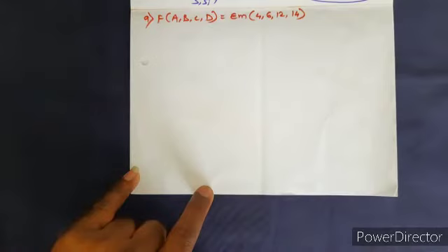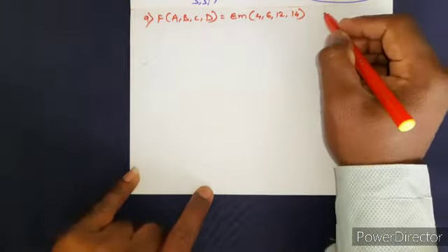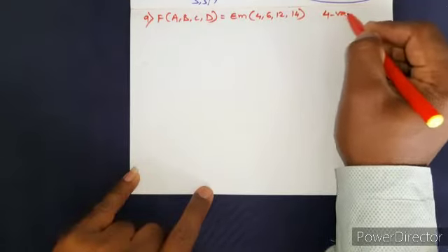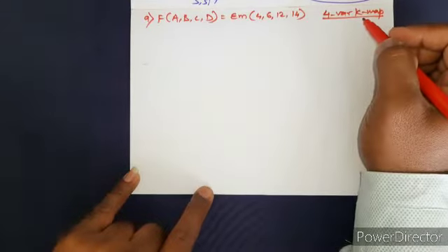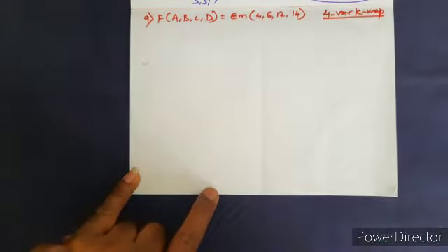In the last lecture we have seen a few examples for 3 variable K-map and some different cases, right? How a group of ones or zeros can be formed. Now in this we are going to look at 4 variable K-map, right? And we'll try to analyze some different cases, some special cases we can say, so that you understand how groups can be formed and how the given expression can be reduced with the help of K-map technique.